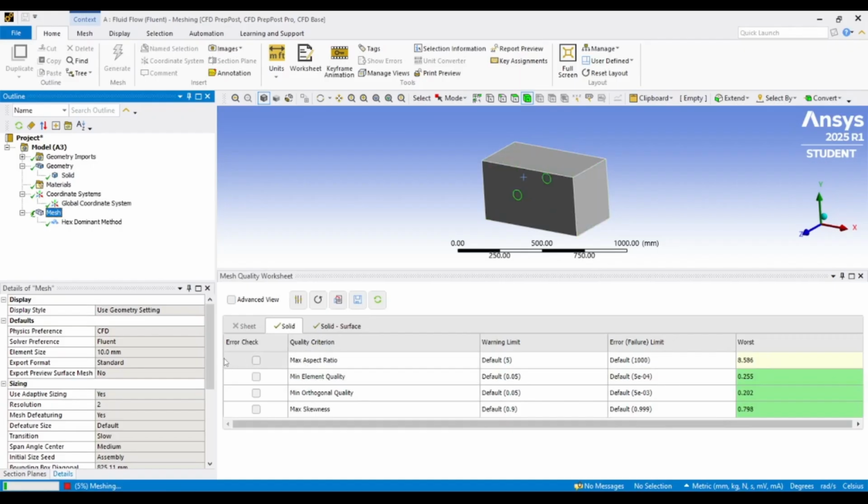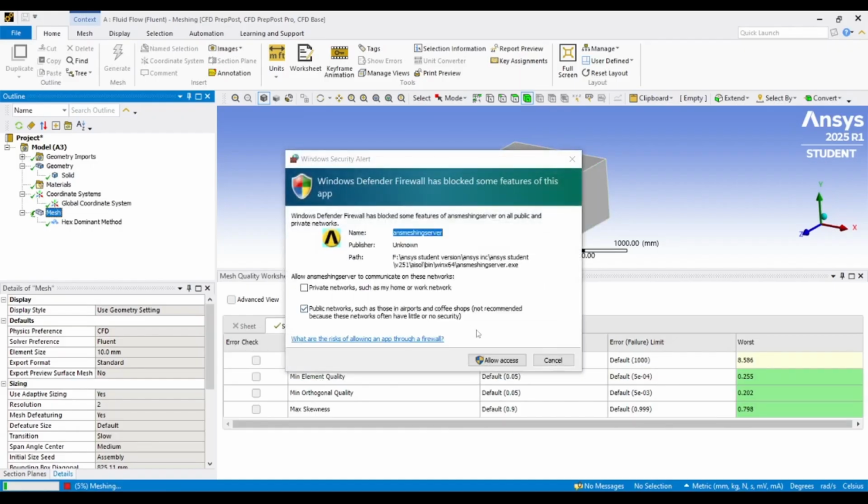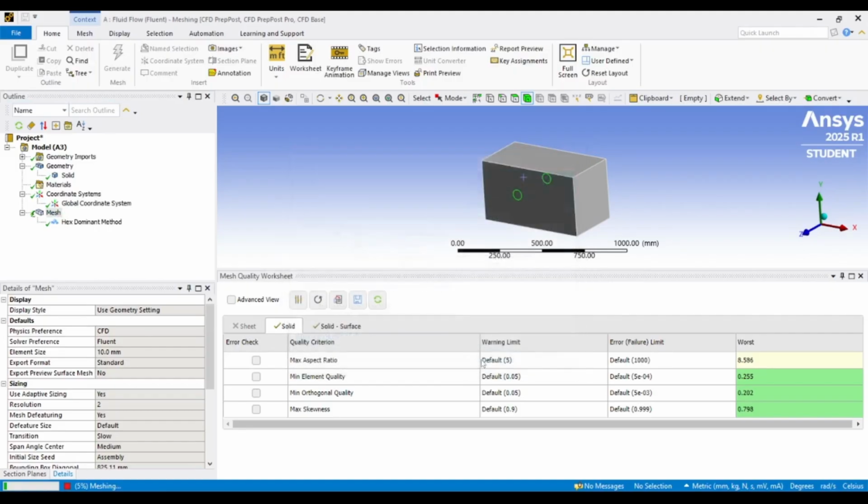Let's begin by examining the pressure distribution around the cylinder. When the fluid approaches the front face of the cylinder, it encounters a stagnation point where velocity drops to zero and pressure reaches its maximum value. This high-pressure zone represents the point of maximum resistance to flow.